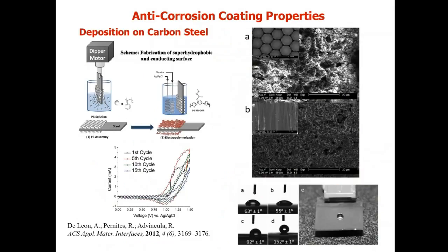These are also coatings that have very high anti-corrosion properties, close to 99% even after 2 weeks of exposure in a salt spray test, an environmental test. They are super hydrophobic, and also there is the hierarchy of the roughness. Basically, what we're taking advantage of here is what they call the Cassie-Baxter effect in wetting, which is a modification of the Young's equation. That means that you have an inability to form a continuous line tension of wetting, and at the same time, the void spaces in this coating result in trapped air.